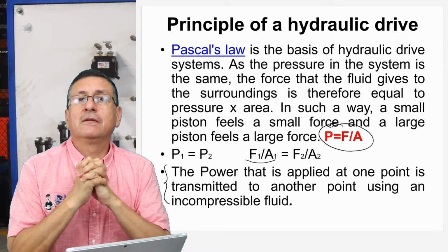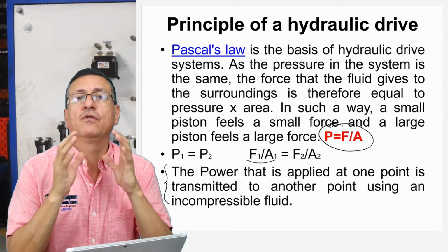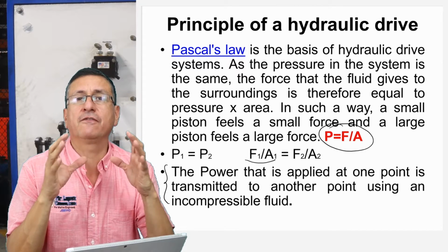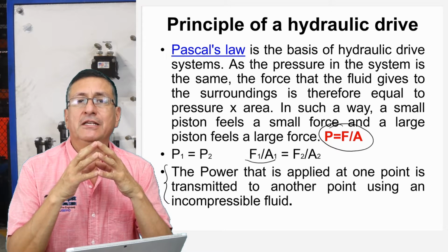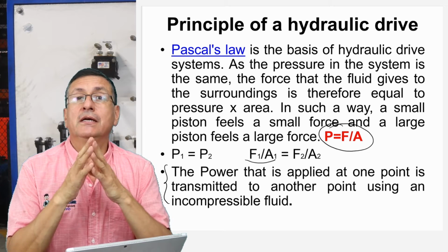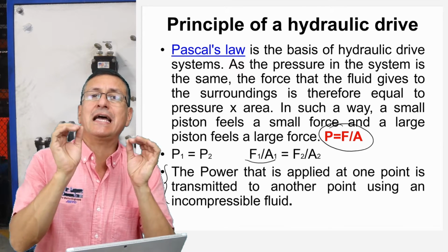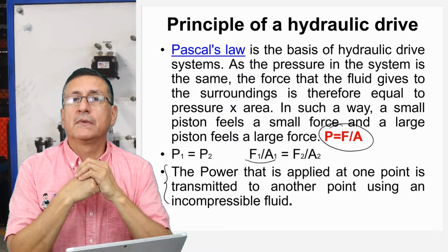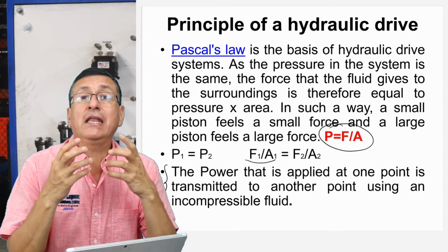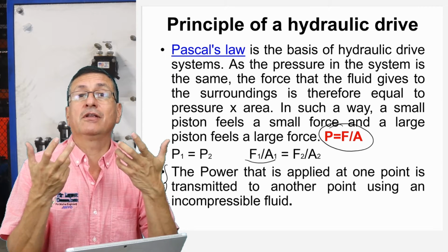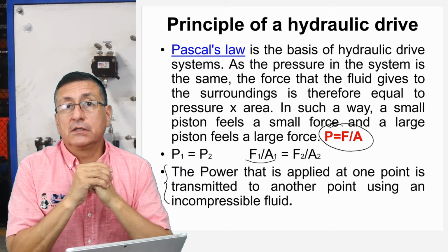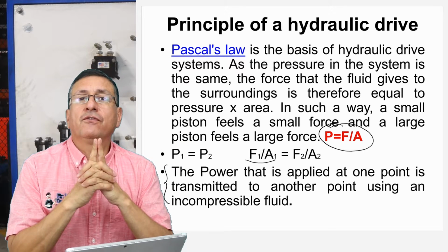The brake fluid is a perfect incompressible fluid because it's impossible to reduce the volume of the brake fluid a little. It's practically impossible. Alright, for that reason, with the brake fluid, you can transmit the force exactly the same in all the points. And we are going to analyze later in the next episode the quality of the fluids used in hydraulic systems and the additives, the components of those additive fluids.